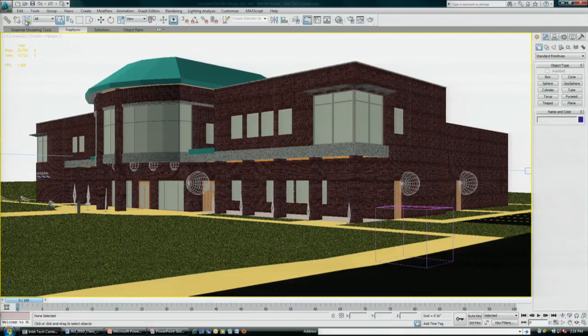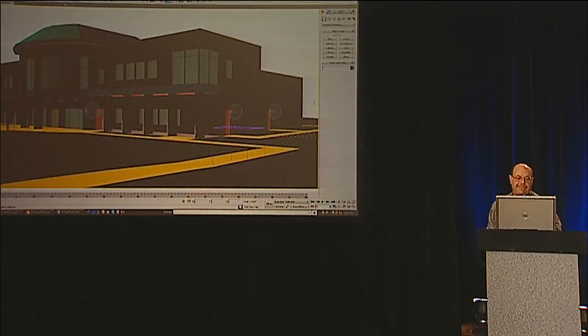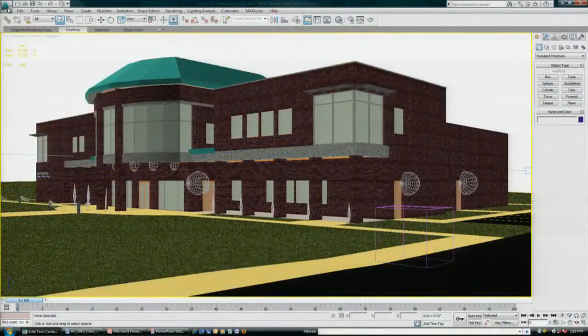In this model, if we go in and take a look, this model is 17,000 square feet. Now, I'm probably running a little bit of inferior equipment against this model. This model will take in excess of 7 gigs of RAM to manipulate adequately in a workflow. So when you're doing BIM inside of Max, you're really looking at some overhead here. Now, we don't have multi-threading yet until we hit the render button. So sometimes you get processor limited before you get memory limited when you run these applications.